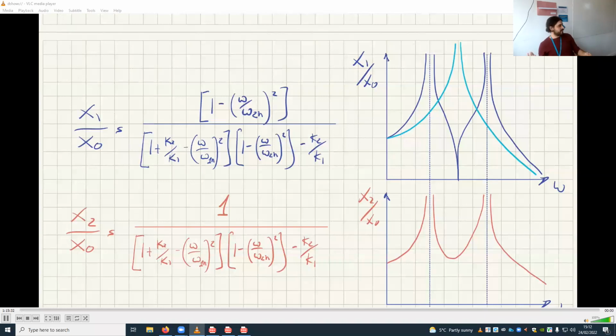Problem is, you never get something for nothing. So in order to get this advantage, you are getting a disadvantage. The disadvantage is that you are creating 2 instead of 1 resonance frequencies. So now we have 2 potentially breaking conditions. But as long as it operates in between these 2, everything is fine.